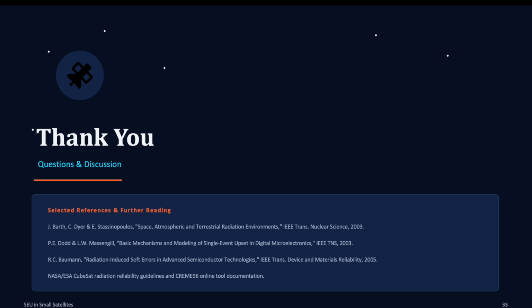But one important thing also: they made a radiation test with a high energy proton source with the same hardware, and then they made a probability function for when the single event latch-up or single event upset occurs. So you probably require some test results, then do some Monte Carlo simulation afterwards. Most of them are probability-based simulations.